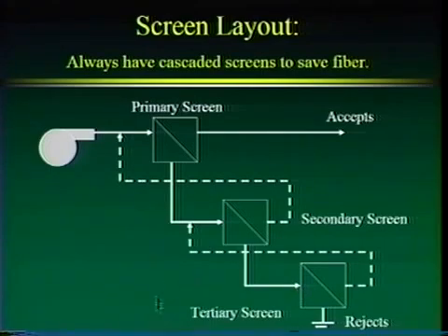So if we take a look here, here's our feed pump to our primary screen, and that's going to mix these two flows. It'll go through the primary screen. Our accepts go further on into our process. This primary screen, it's very important that this has a good cleanliness efficiency because this is the gatekeeper. This mainly dictates how clean this accepts pulp is going to our next operation.